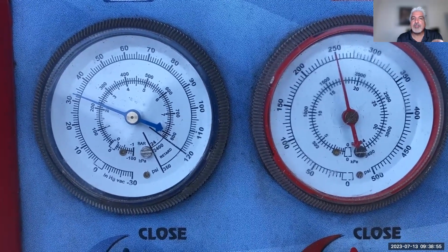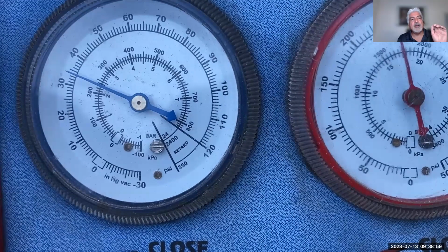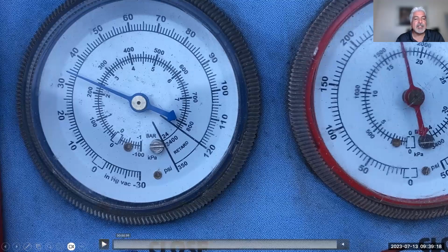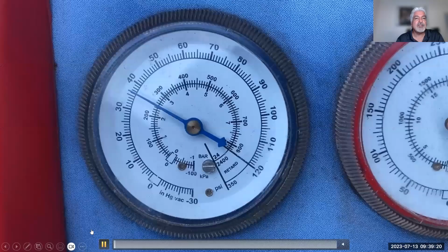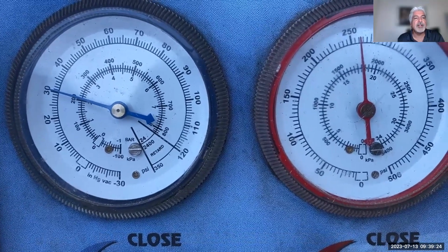What I'm trying to show you is that if I'm analyzing a TXV system and holding the RPM steady, I was holding it at 1200 RPM, and it's blowing nice and cold across the dash, I want to observe the performance of that TXV. This is what should be happening, because it's going to get cold and eventually has to close to control the flow of that refrigerant. So that's what we see going on there.